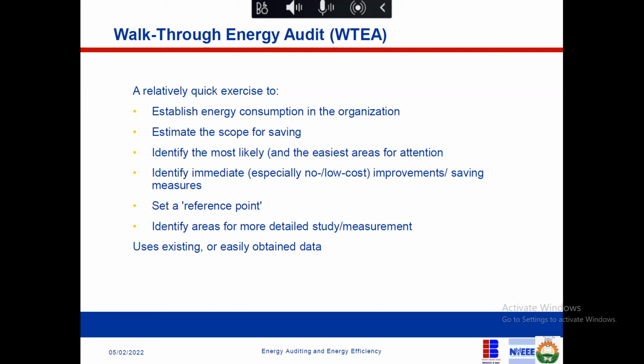So what we quickly did was to make a recommendation, because it was a walkthrough audit, but which really came up with something very significant. We said, okay, you need to provide an elevated tank. It's very important, so you can pump water one-off to the upper tank and then allow it to flow by gravity. So you don't need to be pumping and pumping, which is a key energy consuming appliance.